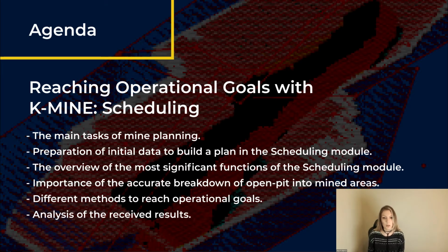We have a block model with a regular block size of 10 by 10 by 10 meters. And as a mineral, we use iron ore with the quality indicators of ferrum total and ferrum concentrate. The rocks with the rock code number 2 are considered high-grade ore, and the rocks with the rock code number 4 are considered low-grade ore. And all other rocks are defined as waste.